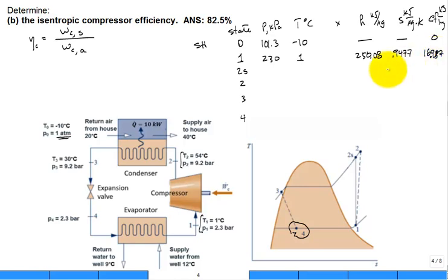How do we get the flow exergy? Well, we've done that before. Say we're calculating the flow exergy at state 1. It's just E sub F equals the enthalpy at state 1 minus the enthalpy at the dead state, which I didn't write up here, but if you evaluate it, it comes in real close to 244.7, and the entropy is 0.9918.